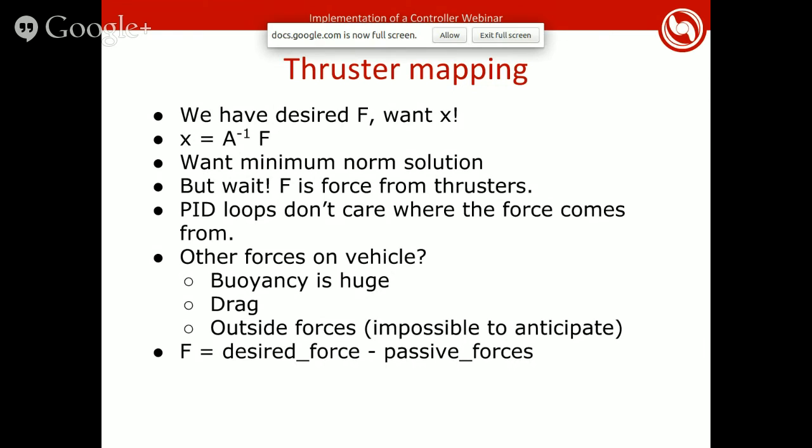The PID loop says, I want an angular acceleration. And the controller is like, okay, I'll give you an angular acceleration with my thrusters. And it does that. But there's also a passive force that tends to roll the vehicle upright, right? That's gravity and buoyancy working together, kind of like passive roll control. Then both of them are acting together, and the vehicle ends up overshooting the 0 roll and just oscillates in the cradle.